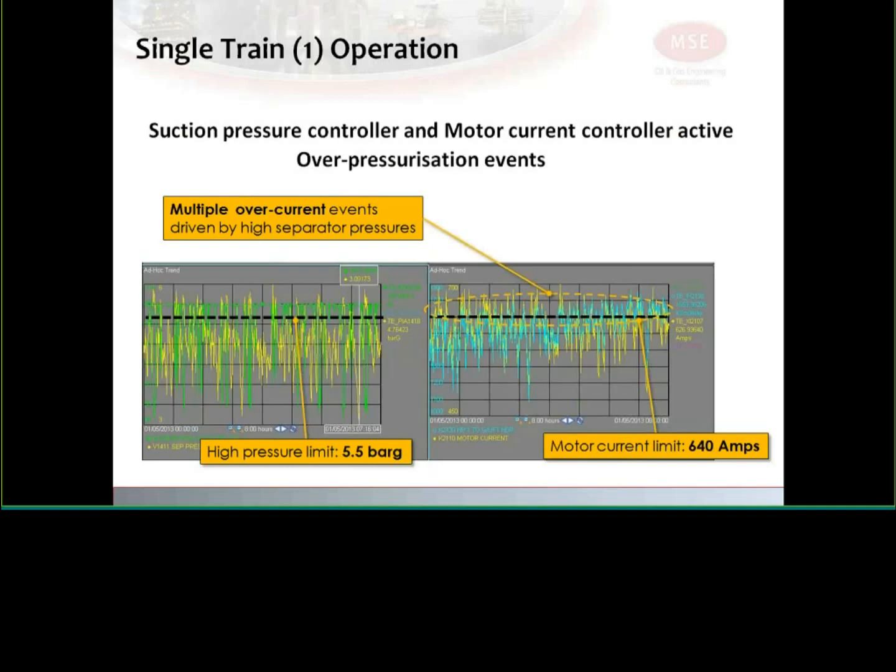So automatically, the throttle valve and the control interactions have been reduced by two different elements. The only thing that is active in this case is suction pressure override control on the throttle valves, which is also controlled by the master controller, like Mark explained earlier, and the power limiting controller.